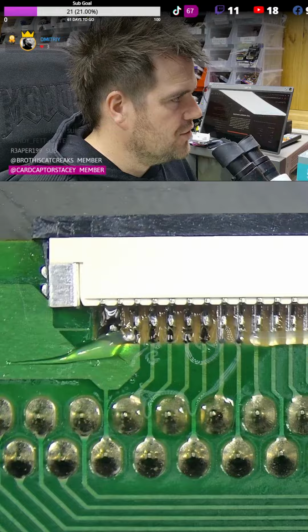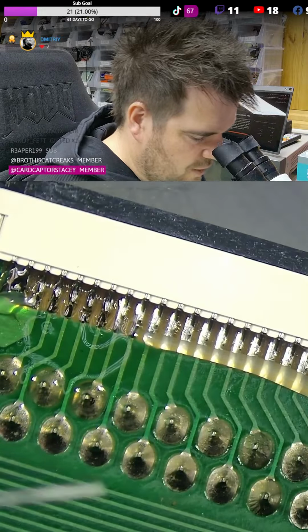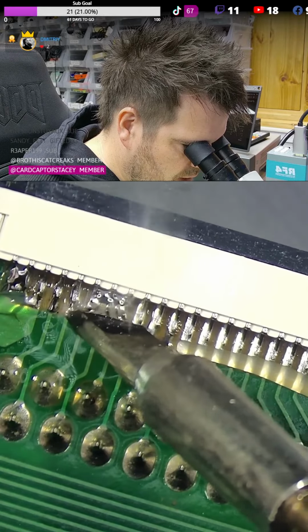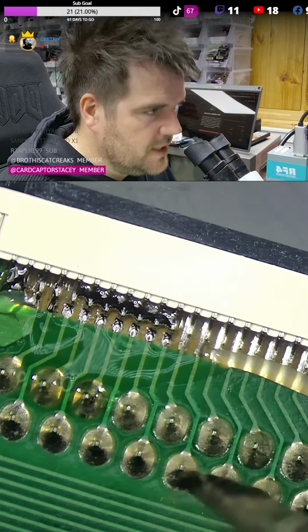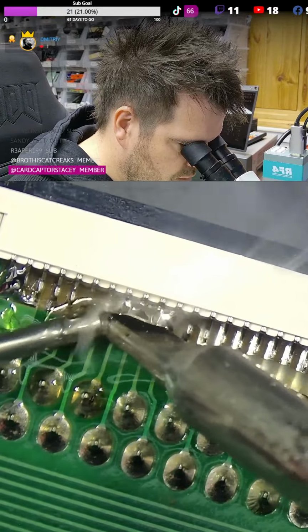What you can do, though, on most connectors, some connectors just have a pitch that doesn't suit this method, but what I tend to do is just drag solder. So let's give it a go. Just flood your iron with solder, get a big ball on the connector, and just drag down slowly. And if you see it's already bridging, flux on, go back up, drag down.